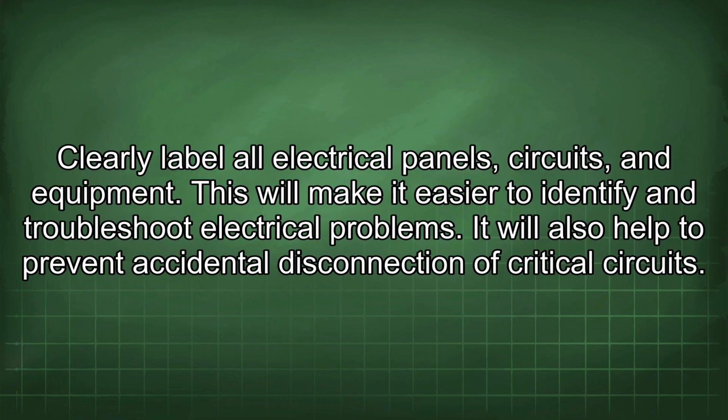Clearly label all electrical panels, circuits, and equipment. This will make it easier to identify and troubleshoot electrical problems. It will also help to prevent accidental disconnection of critical circuits.